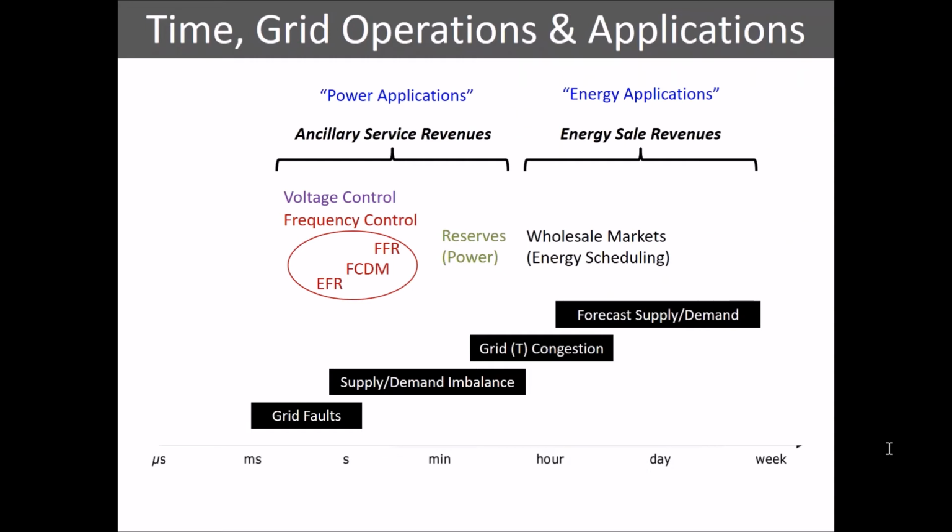There's one other acronym on there that I don't think I mentioned, which is this FCDM. That's Frequency Control by Demand Management. Now that's important. It's a kind of UK acronym, but the same kind of thing will appear under different names in different countries. The importance of that is that whereas in the past we've tended to focus on changing supply to cope with all these supply-demand imbalance problems, that's by definition demand management. It's recognising that demand flexibility is going to be important going forwards to solving some of these grid problems.